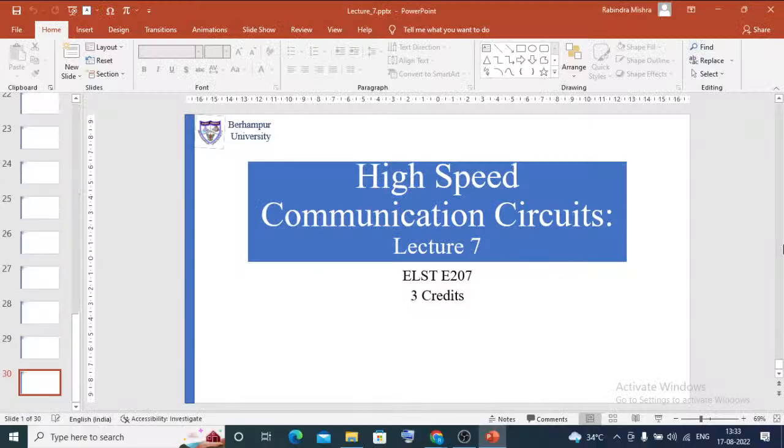So with that, we come to the end of our discussion on even mode and odd mode analysis. We saw two examples. One is a pure electrical circuit. The other is two coupled lines. In the electrical circuit we found the admittance matrix as an example. For the coupled lines we found the characteristic impedances.